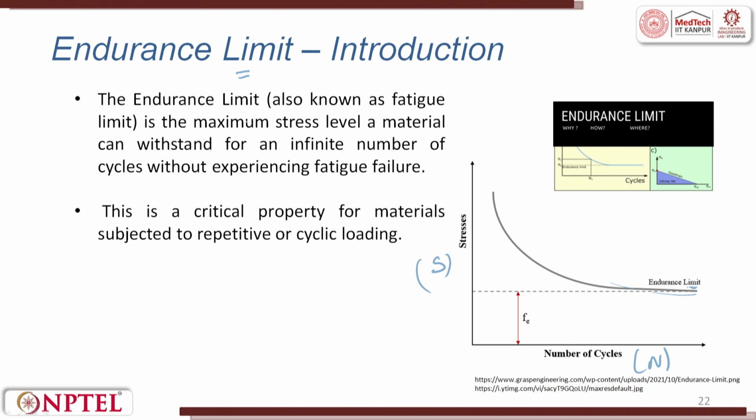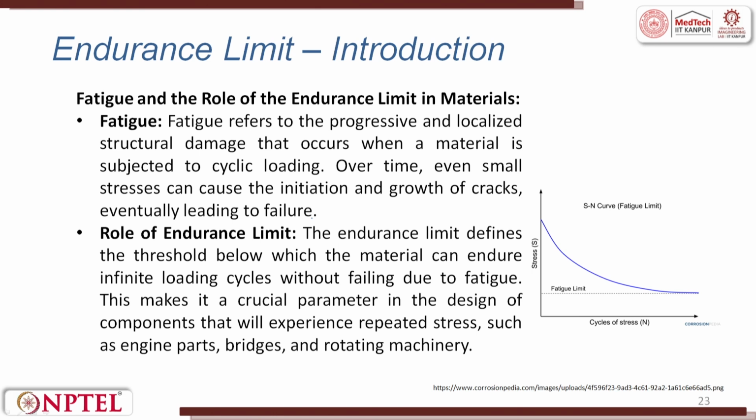Endurance limit, also called as fatigue limit, is the maximum stress level a material can withstand for an infinite number of cycles without experiencing fatigue failure. This is a critical property for materials subjected to repetitive or cyclic load, which is generally used in bearings.